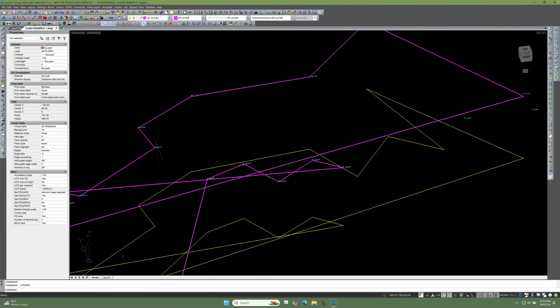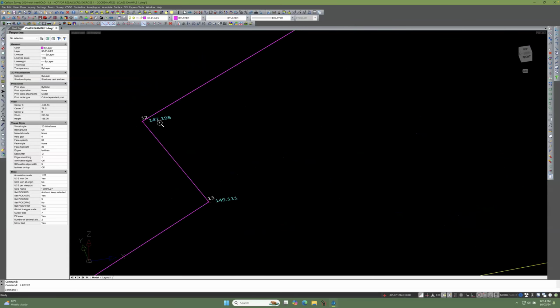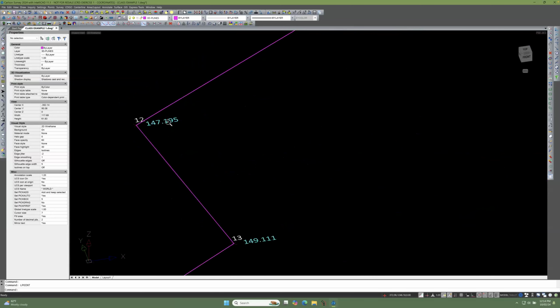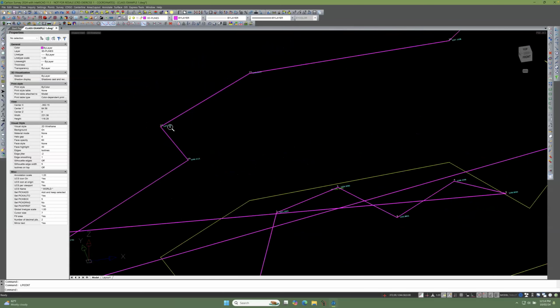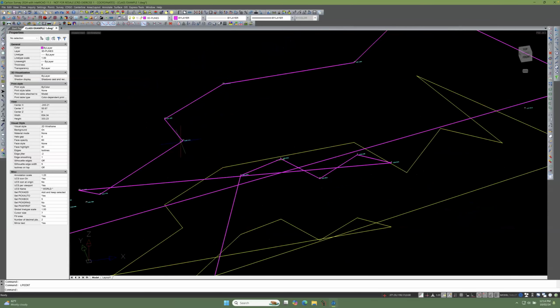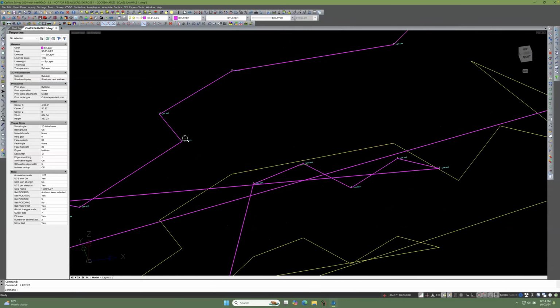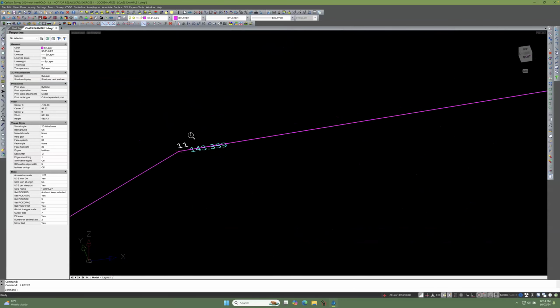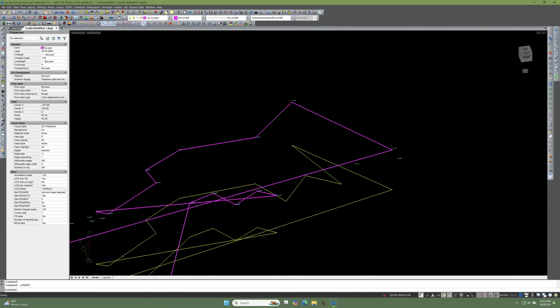They're always at their right elevation. You could have drawn the points down at 0, even though they have elevation, and when you draw this 3D polyline and use the point numbers, it puts the polyline up at that elevation. But to me, I like to see it because I can visually verify that. And so that can be done as you draw locate points.